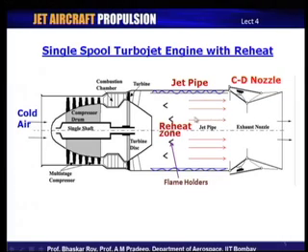Now, let's look at this jet pipe a little more. What you are doing here is raising the temperature to very high values all over again. Since the gas temperature is going to be very high, you create a process through flame holders and other means, very cleverly, so that you have a uniform temperature profile a little later after this reheat zone, and this temperature is quite high.